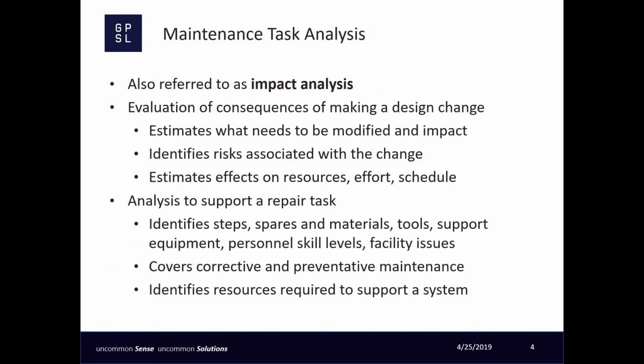When we talk about maintenance task analysis, what do we mean? In the aerospace and defense world, maintenance task analysis, or MTA, is the process of identifying the steps, spares, materials, tools, support equipment, personnel skill levels, everything necessary to complete a repair task. This includes both corrective and preventative maintenance. When an MTA is complete, it will include all the resources required to fully support a system. Maintenance task analysis often occurs with or without the digital thread.